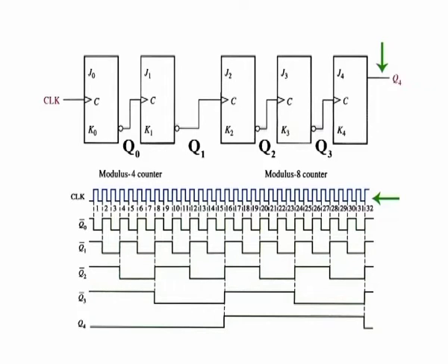When operating synchronous counters in a cascaded configuration, it is necessary to use the count enable and the terminal count functions to achieve higher modulus operation. On some devices, the count enable is labeled simply count enable or some other designations such as G, and the terminal count is analogous to ripple clock output on some IC counters.